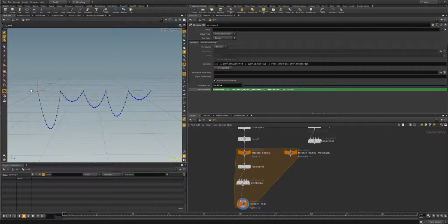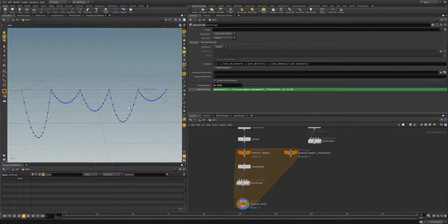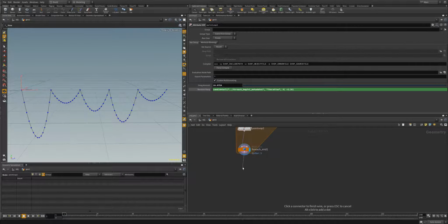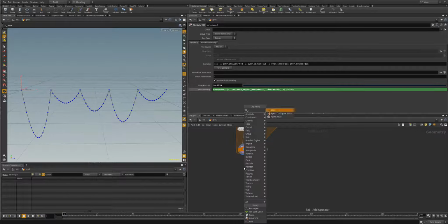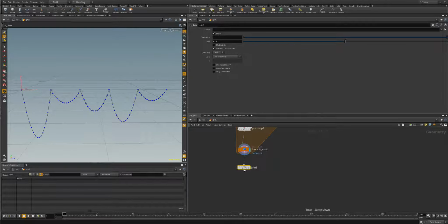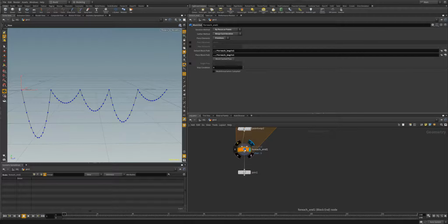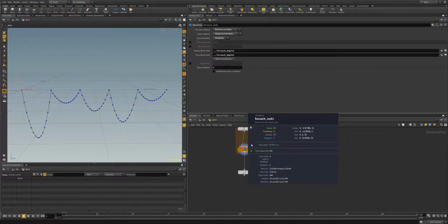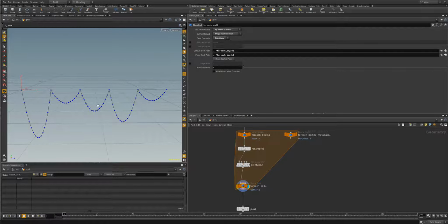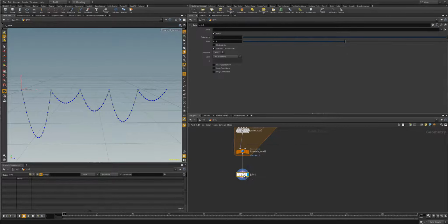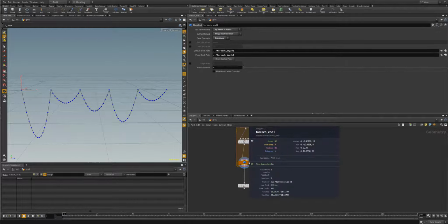how we can add some points and extend them off of the end of our curve using the polyframe point VOPs and some point attribute expressions. So we'll just drag this off of here, and first thing we're going to need to do is create a join node, and I'll take a look here. We'll see that again we have 5 polygons, where we want this to be one continuous polygon curve. So our join node will actually combine all of those polygons and clean up our overlapping points and vertices that we would have here.